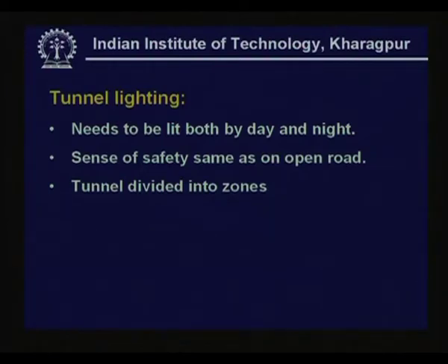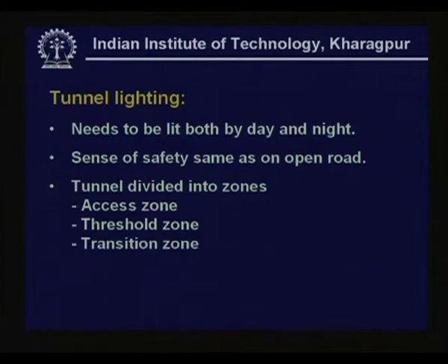Therefore, in trying to do this, the tunnel is divided into zones. The zones are the access zone, just a little outside the tunnel; the threshold zone, the entry to the tunnel; the transition zone, from the outside environment into the tunnel; the interior, the tunnel proper; and the exit zone.